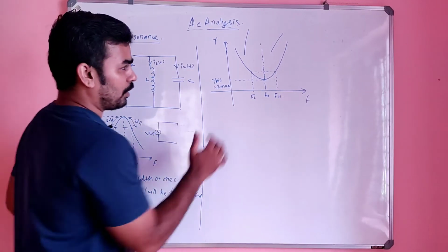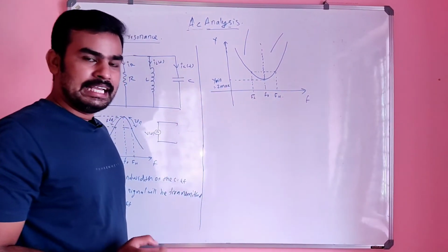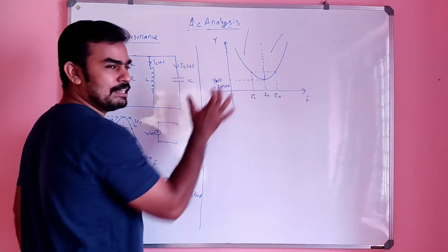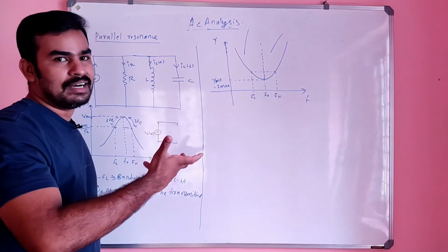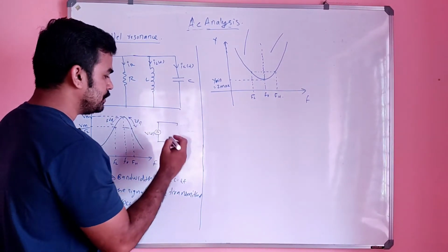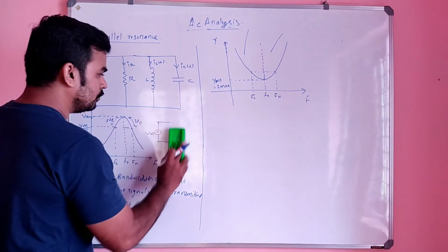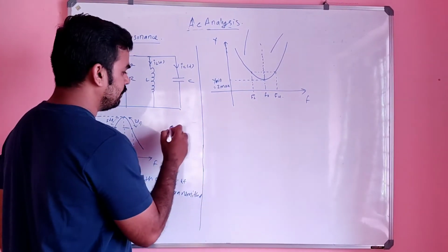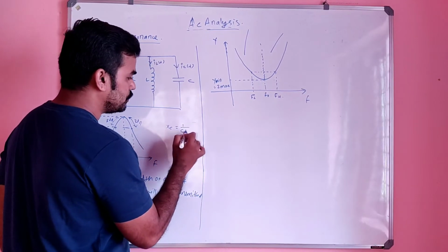1 by impedance. So for lower frequency, in a series resonant circuit, capacitance is more predominant, because whenever frequency is less, we know the capacitive reactance XC is equal to 1 by C omega.